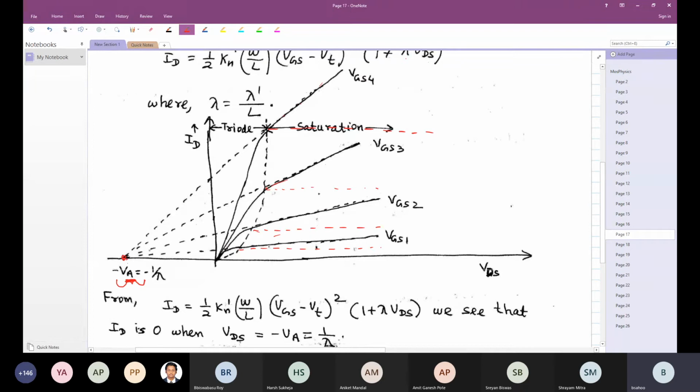Now, why did we do this? Because in this course, we wanted to use exactly similar models, from a circuit perspective, to analyze both BJT and MOSFET circuits. Both BJT and MOSFET work on two different physical principles. The physics is different, but from a circuit's perspective, we can treat them almost identically because we can develop a unified model for them.